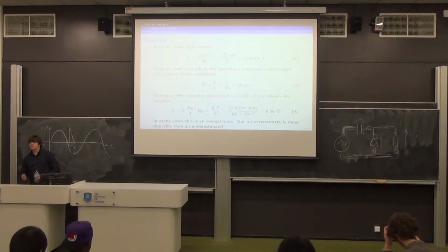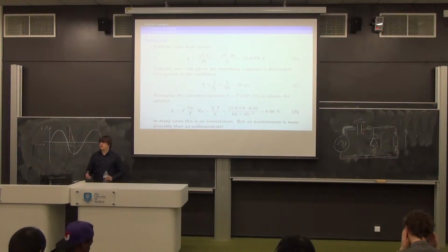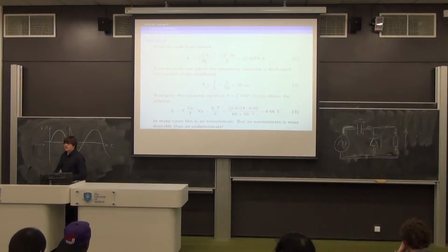So what I'm saying is, way back when we started on diodes, I said you can say it's either reverse bias, nothing happens, 0 volts or more, perfect conduction. And I said, well, hang on a minute, you really need 0.7 volts as well, because that's how much voltage you need to get conduction. So we started using a 0.7 volt voltage source.